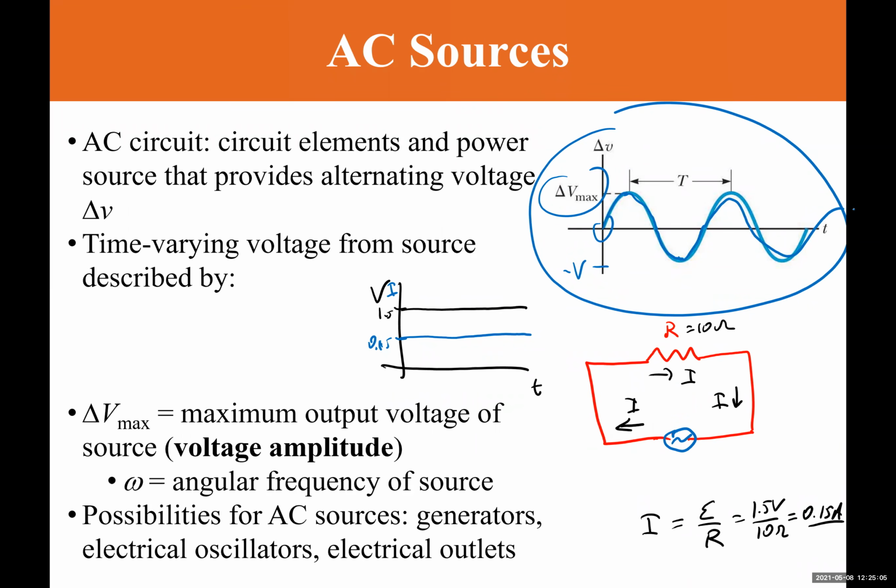And you can see it's alternating. So what you end up getting here is an alternating voltage. It always goes back and forth between its maximum value and minimum value, which is positive and negative. And when you take the measurements and put them on a graph, you will see that basically it's sinusoidal. So that means the voltage is time varying, and you can look at it as a period: how long does it take to get to its maximum value again. That means you can look at it in terms of frequency, or the period, and represent it as a sinusoidal graph.